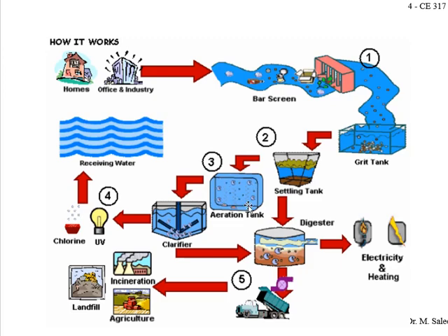The bacterial cells will grow and the waste will reduce. In the next step, we put this in another clarifier or sedimentation tank where these heavy bacteria, which have become bigger now, will settle, and from the top you can get cleaner water. Up till here it is called the secondary treatment.